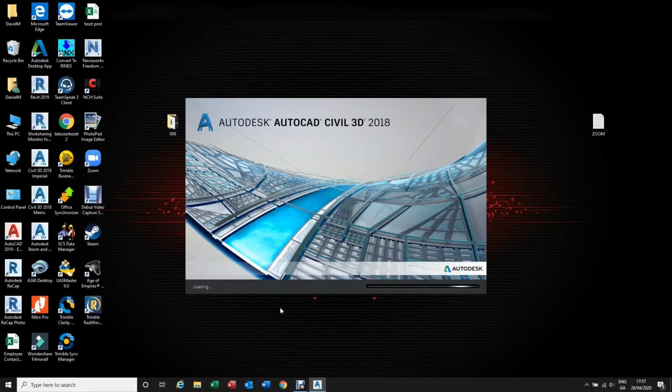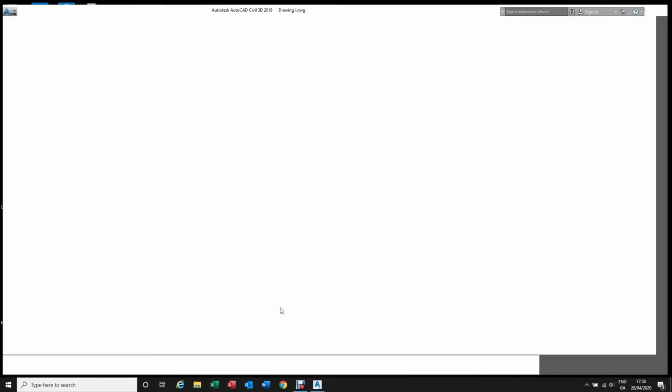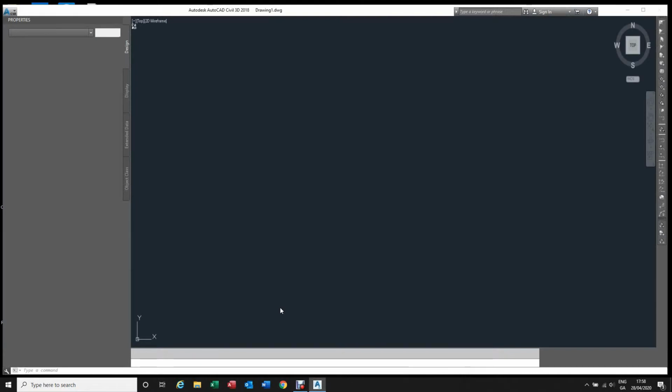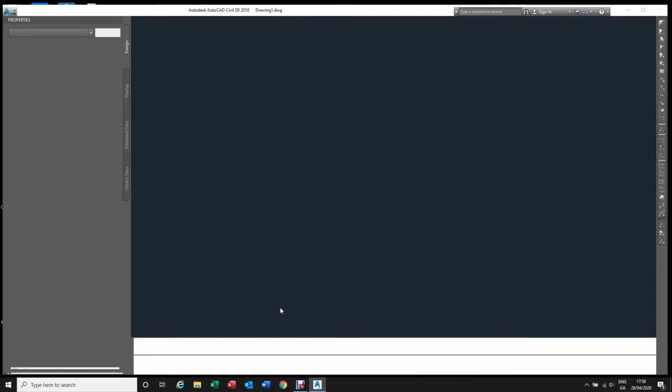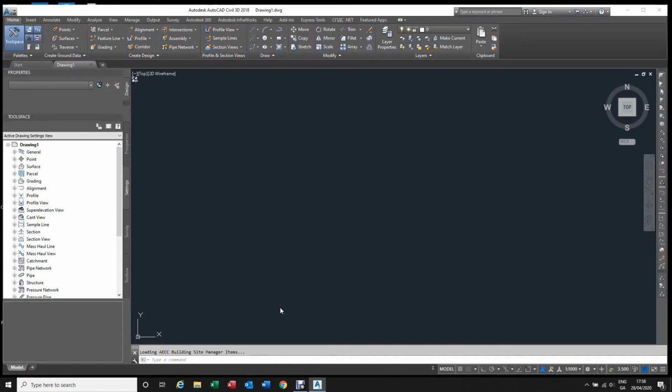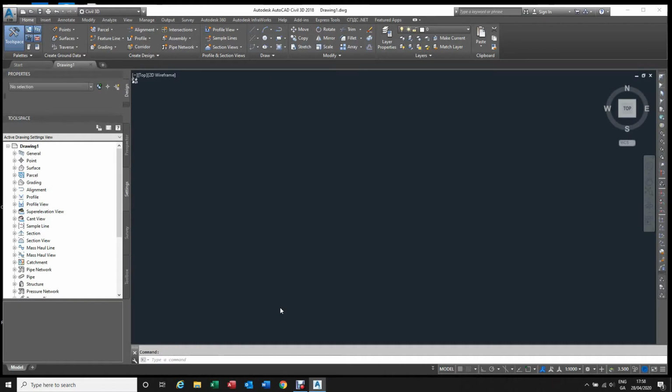This data came from a TX8 scanner and it was registered with Trimble RealWorks and also processed a little bit. I used automatic cleaning methods, indoor floor auto extractions, sampling also. I tried basically everything I could, and still a little noise left, I think. When I'm looking on the front view, you can see a little bit. I tried to cut out everything, but it's almost impossible for me to do. So I will work with that. It's a pretty good one.